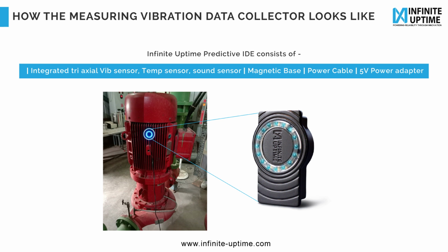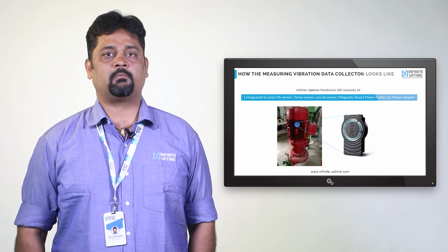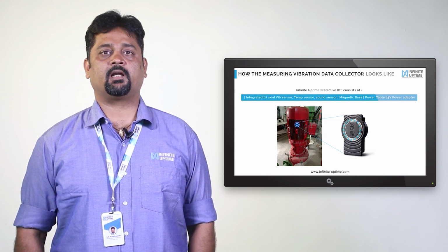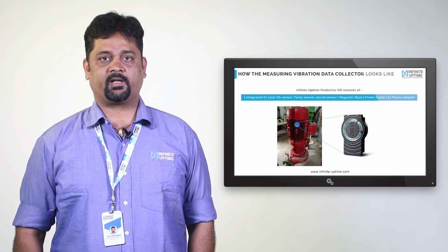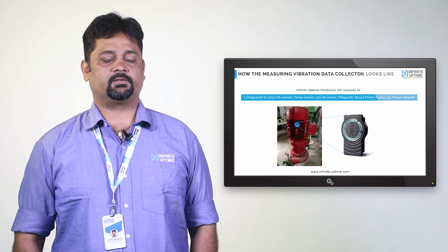You also need to understand what the vibration data analyzer or collector consists of. Take an example with Infinite Uptime's IoT-based predictive IDE. It consists of an integrated triaxial vibration sensor, temperature sensor, and a sound sensor. This comes along with its magnetic base, which eases mounting applications and can also come with a stud mount arrangement for permanent mounting techniques. It has a power cable with a 5-volt power adapter. This is how it looks.